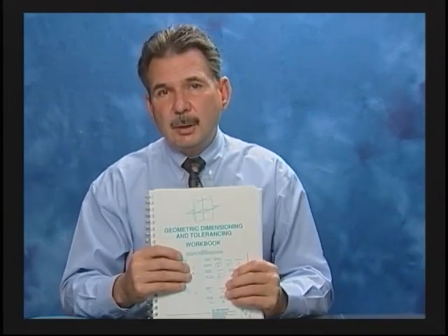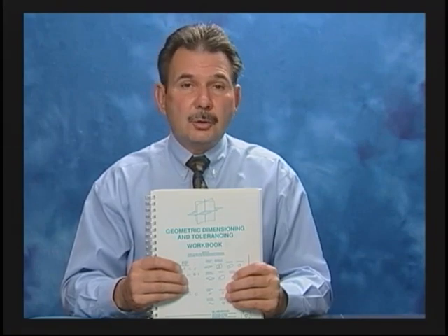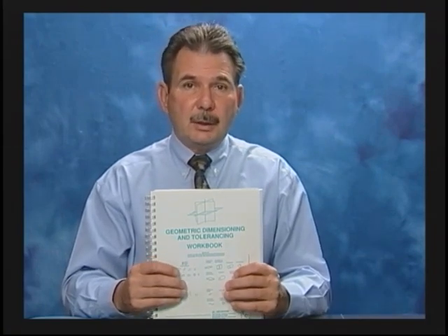So I don't want you to just put numbers in from thin air. I want you to calculate these numbers. I want to know where every number comes from on here. These are some very common formulas that you use in the geometric tolerancing for the fixed and floating fastener formulas. You'll find that information in the geometric tolerancing workbook, I think in chapter 15, and it also talks a little bit about projected tolerance zone.